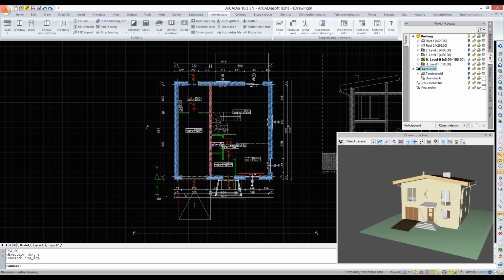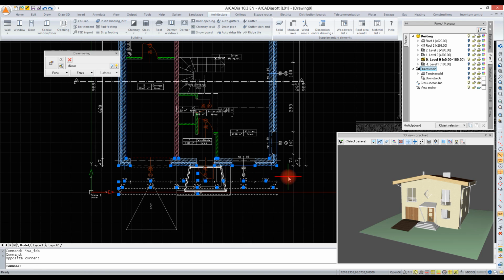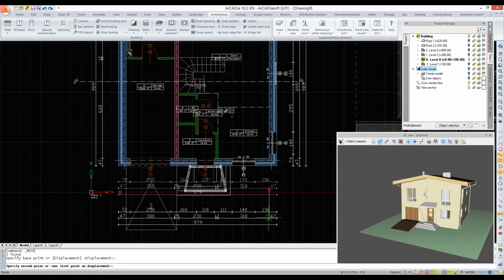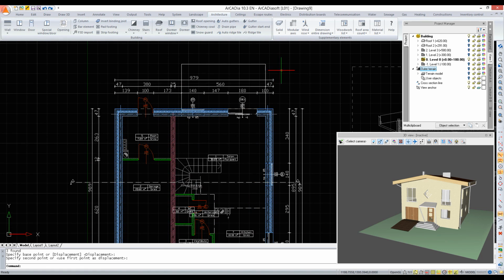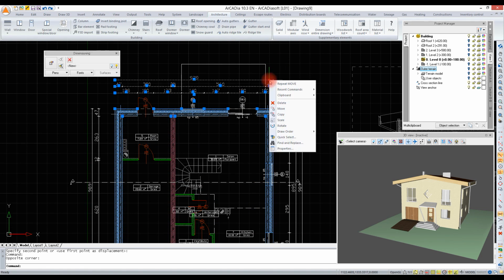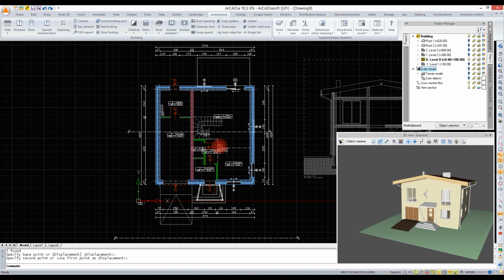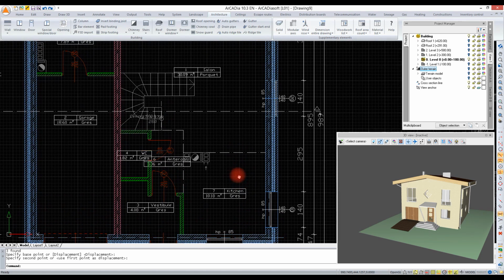If you click on OK, dimensions will be inserted. Dimensions will stick to the elements, which means that if you choose, remove or move any element that has been dimensioned, like window or door, then of course the dimension will also be modified. I move some of these dimensions so that they will not overlap on anything. Dimensioning the entire drawing involves dimensioning the exterior.